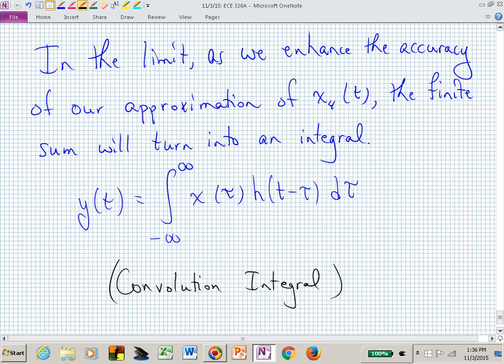This is some way of multiplying these time domain waveforms, and in fact, we are going to say that h, in this case, is flipped. The variable of integration is tau. We're actually negating that. That's what I mean by flipping it. And for t, we want to find y for all time, from minus infinity up to infinity.